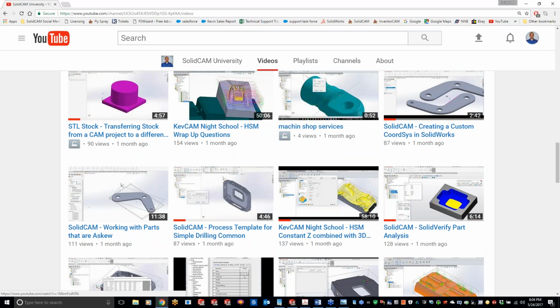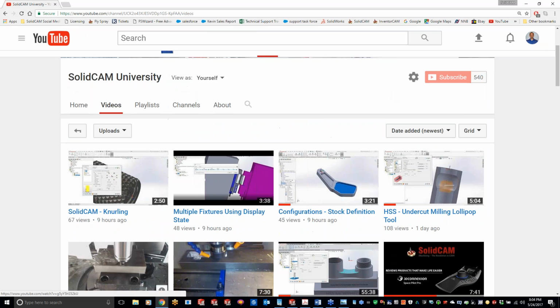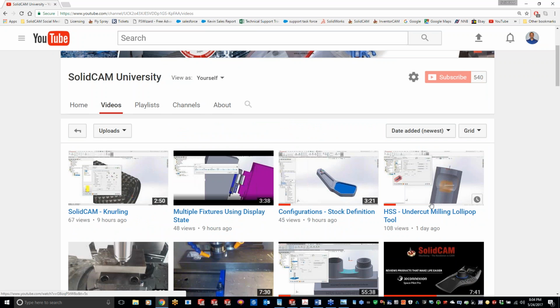And George, I think you sent me an idea on undercutting. So we do have an undercutting video right here on how to use HSS undercutting with a lollipop cutter, just for finishing up those bottom side radiuses, or if you had an actual flange-out kind of part right here, like you can see.